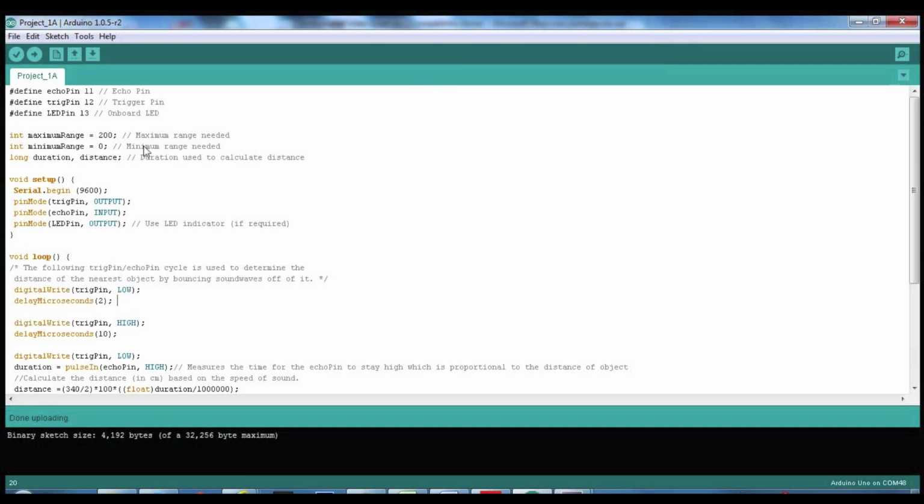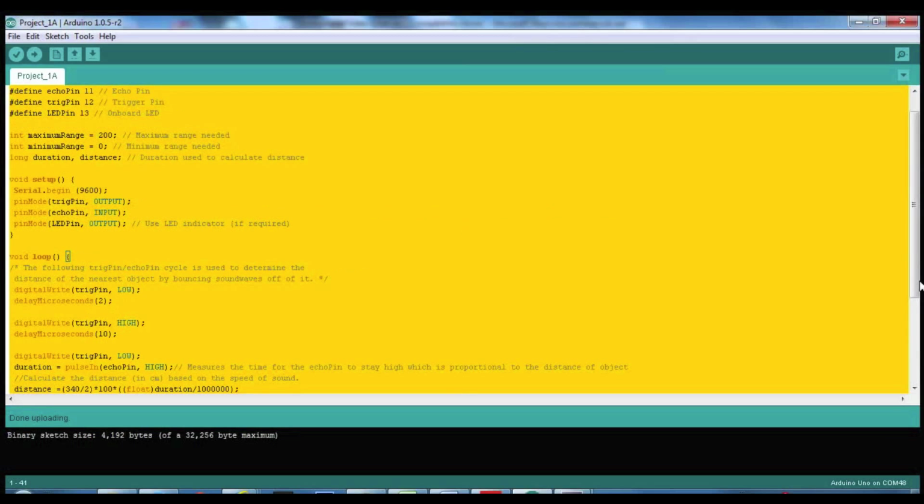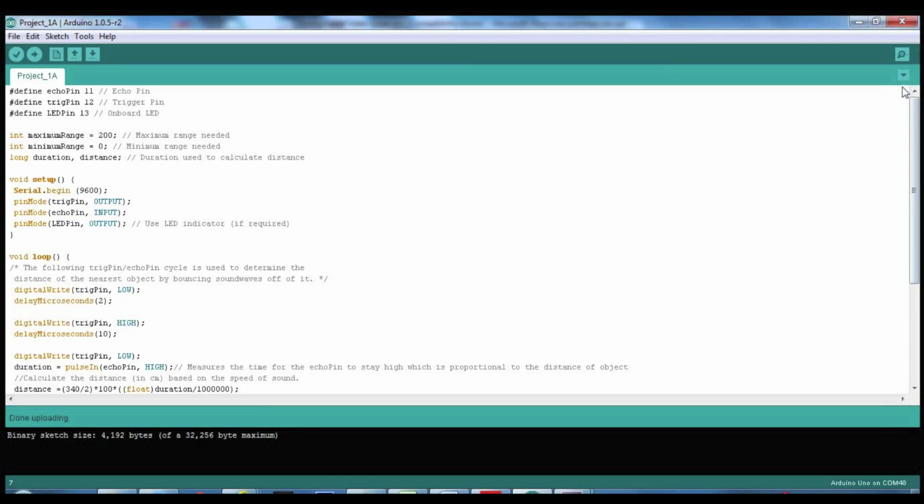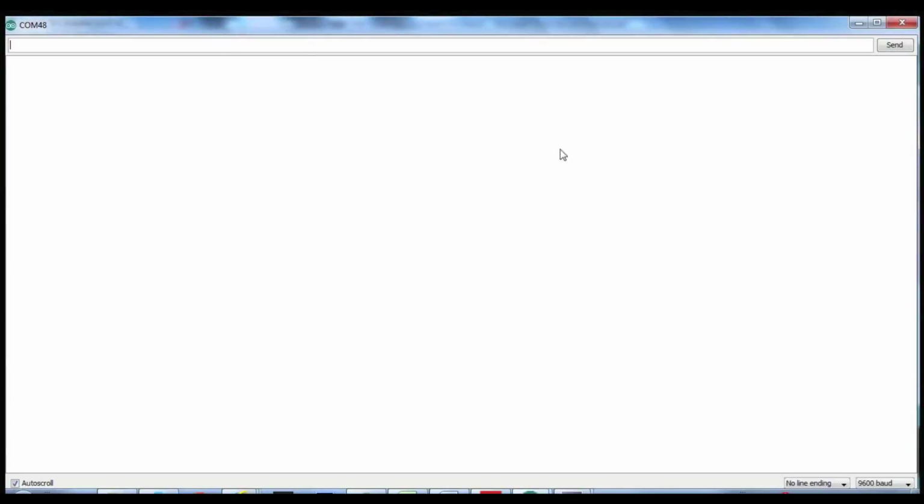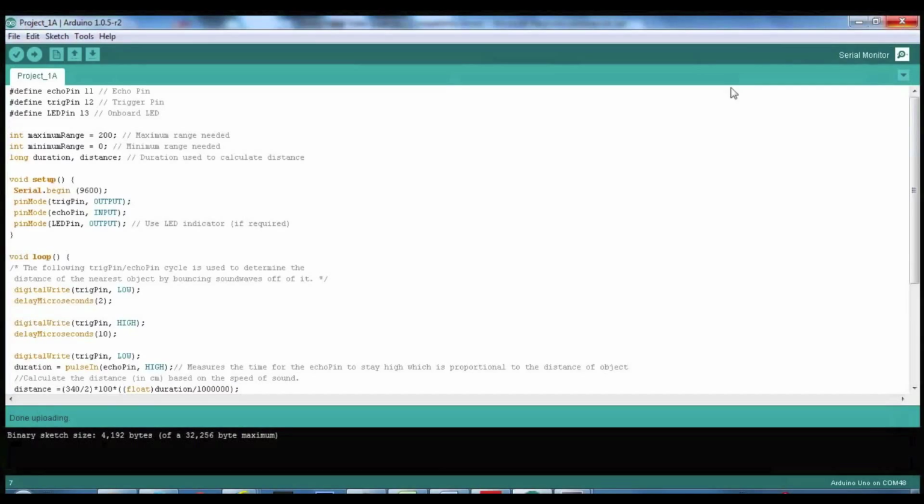For basics, there are 3 things in your Arduino user interface to take note. Firstly, what you see here is a scripting page where your codes are written. They term it as sketch. Secondly, you also have a serial monitor where you can print live serial readings that your Arduino is taking from the sensory components. Basically, Arduino reads voltage changes, which are represented into numbers you see when you use the serial.print related commands to show the readings in the monitor.